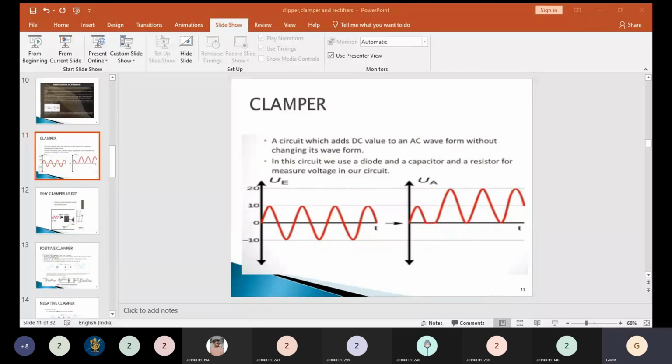See this question, 40% efficiency of rectification does not mean that 60% of the power is lost in the rectifier circuit. In fact, the crystal diode consumes little power due to its small internal resistance. The 100-watt AC power is contained as 50 watts in the positive half cycles and 50 watts in the negative half cycles. The 50 watts in the negative half cycles are not supplied at all. Only the 50 watts in the positive half cycles are converted.